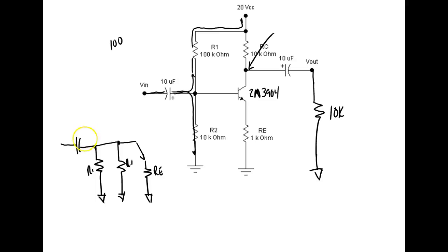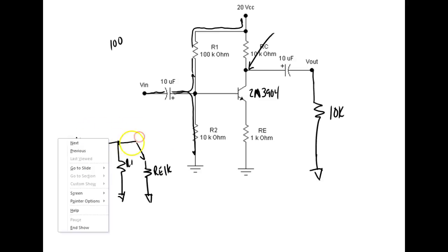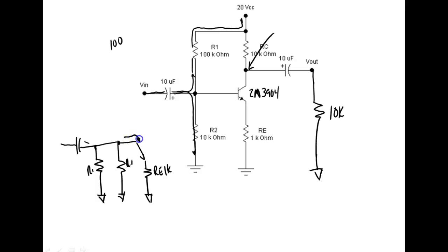So that means if I put, let's say this is a 1K over here, and I put 1 milliamp of current through here, then this guy is going to see it as 100 milliamps. And actually it's going to be a little more. Do you understand that? Now, if I came over here and took 1K and multiplied it by 1 milliamp, which is what your input sees, then it would drop 1 volt. Do you follow me so far?